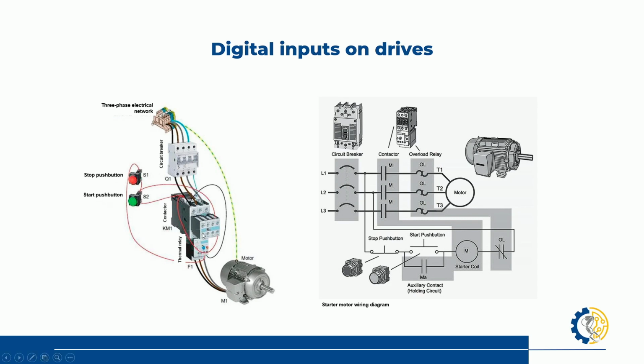Now, how does this work? Remember that our contactor and our relay work thanks to our coil activation. Now, these coils are generally fed with a positive and a negative. There are certain coils that are for AC and DC. If we choose direct voltage or DC, then we're going to go to our control part, which is 24 volts. But we can also feed through a neutral or a phase, which is AC.